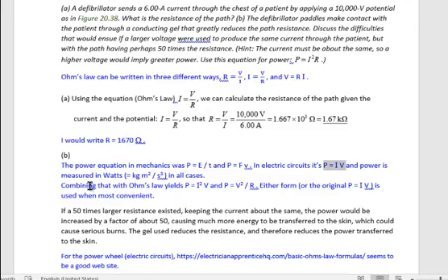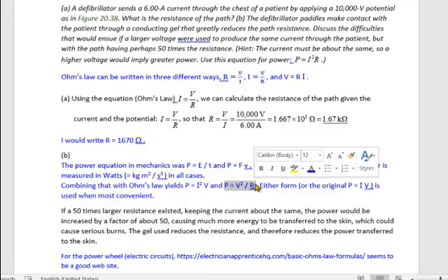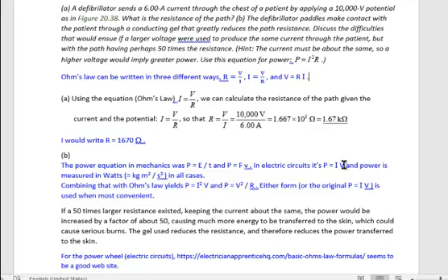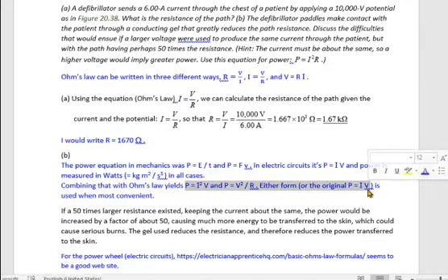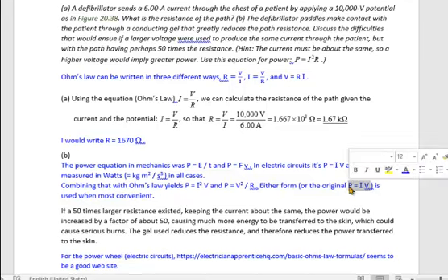There are two alternative ways to look at it when you apply Ohm's law to that. So current equals voltage divided by resistance. You get this one here: power equals voltage squared divided by resistance. Or if you say, okay, voltage equals resistance times current and plug it in here, then you get this one here: power equals current squared times resistance. So these three forms for the power law, again, I only have one of them memorized, this one right here, and then I just use Ohm's law, plug it in, or maybe I do two steps. So I really don't have them all memorized.